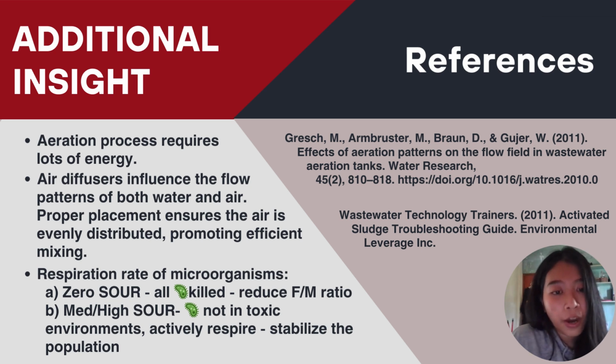to ensure the high efficiency of the aeration process in the tank, we can determine the respiration rate of the microorganisms by determining the specific oxygen uptake rate, or simply called SOUR. SOUR indicates how much oxygen is consumed by the microorganisms to metabolize the organic matter.